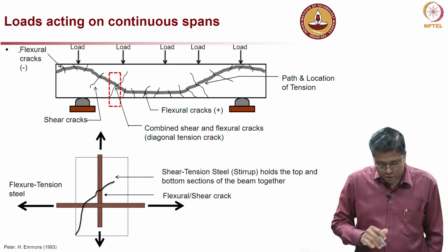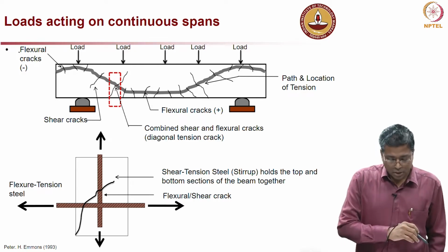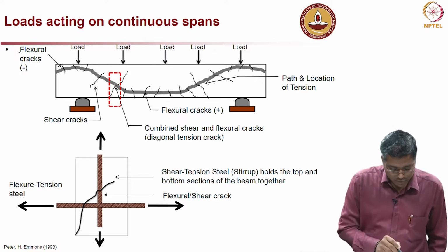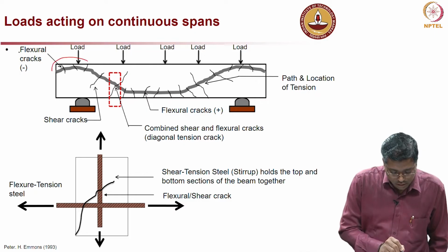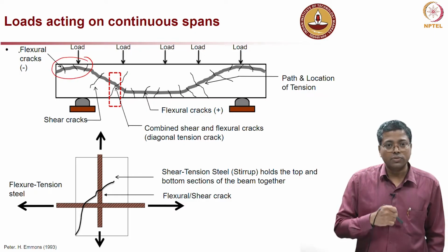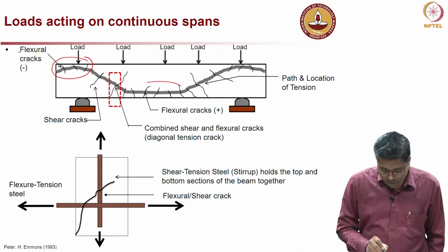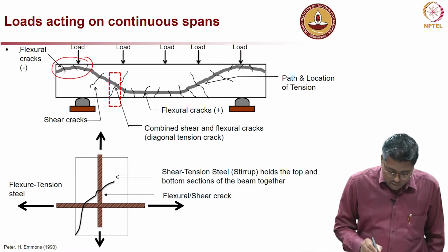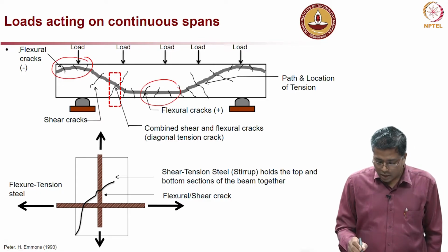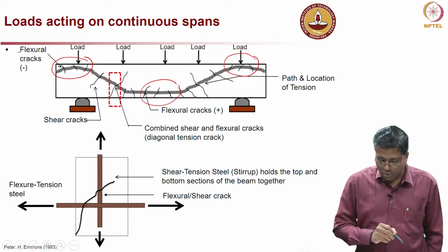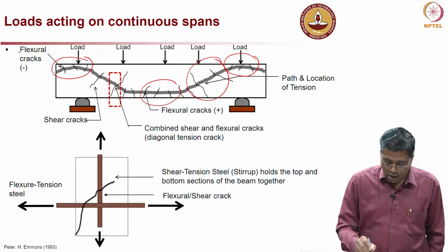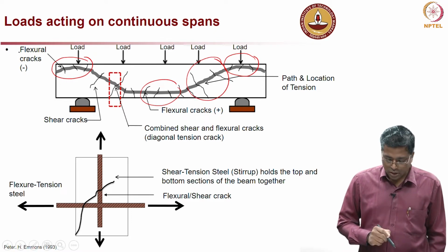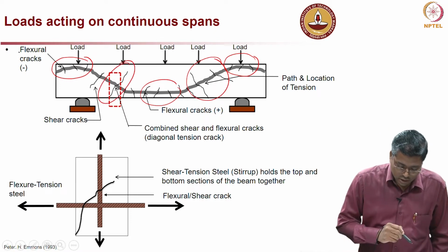Now, loads acting on continuous spans. We are zooming in a little bit on the sketch which was shown in the previous slide. So, you can see here these are the flexural cracks because of the negative bending moment, and these are the flexural cracks because of the positive bending moment, like this here, and then similar negative bending moment cracks, and then we also have shear cracks and combined flexure-shear cracks here.